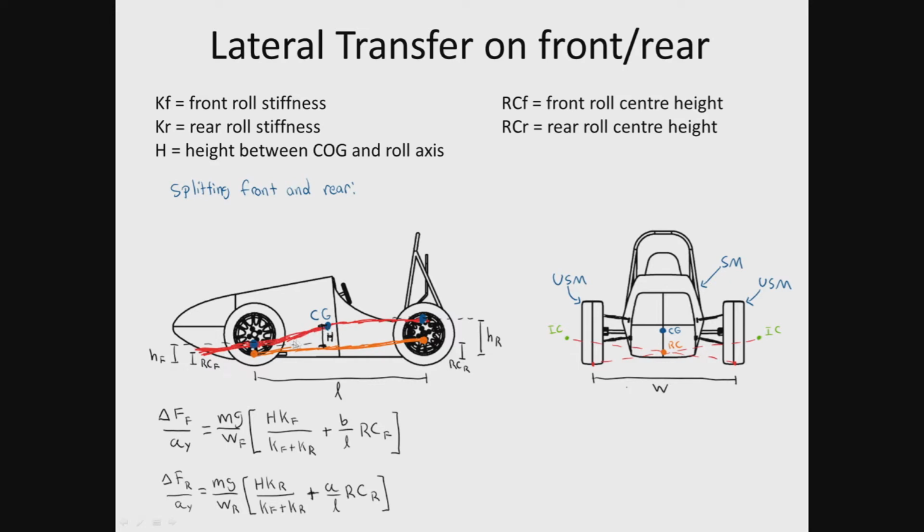So we have what's called the centroid axis here, which is a red line running through our car, which shows a rough representation of how the center of gravity migrates when you look from the front to the back. So it's no longer the true center of gravity because we're not lined up longitudinally, but over top of the front axle and over top of the rear axle, the mass will be concentrated differently. If we only consider mass on the vertical concentration here, the centroid, we'll refer to it as, will be at a different height than the actual center of gravity. And so this comes into our consideration when we're calculating for roll, where the centroid actually exists. The force will act at the centroid rather than the center of gravity itself when we're calculating our roll moment for later. But right now, let's just look at the weight transfer.